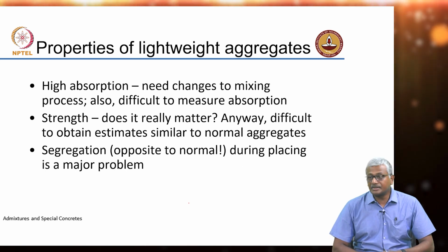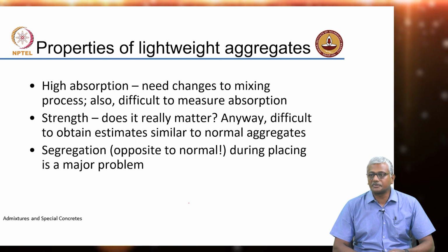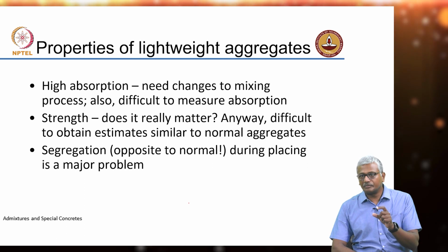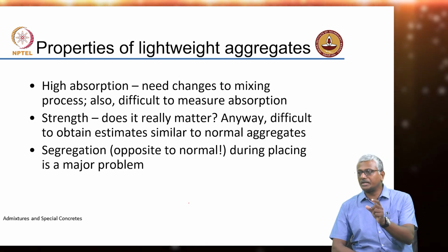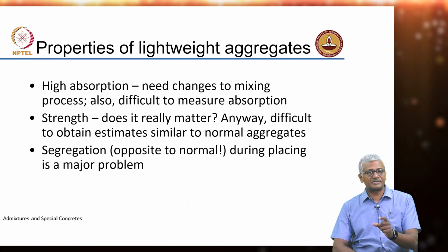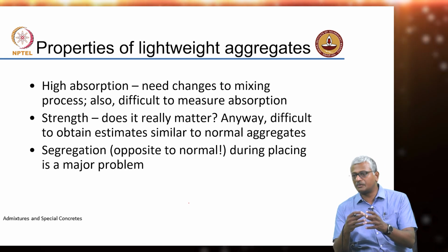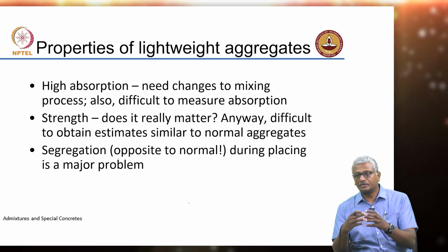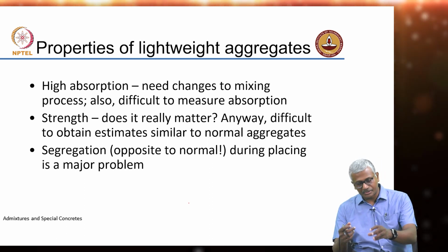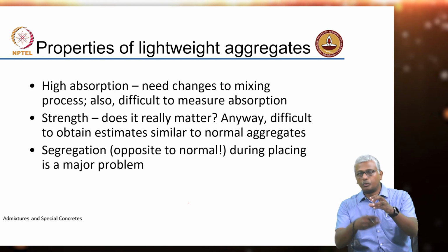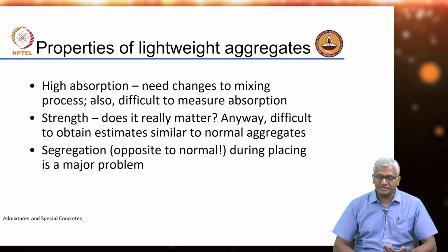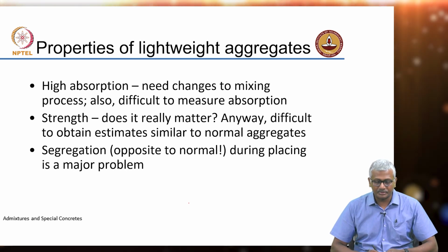Okay. And in some cases it may be difficult to measure the absorption, because the porosity in these materials is so much, because to measure absorption you need to get the aggregate in a saturated surface dry state. What is saturated surface dry? When all the pores of the system are filled with water, but there is no water sticking to the surface. Now, that is very difficult in a system that is very porous, because as soon as you remove it from the water, the pore water also will start draining out. Okay. So, getting SSD condition is not very easy. So, measuring absorption is also not easy.